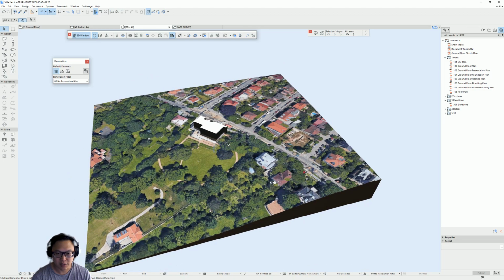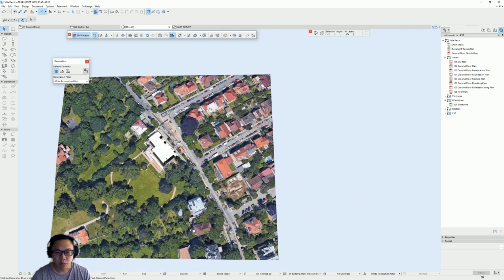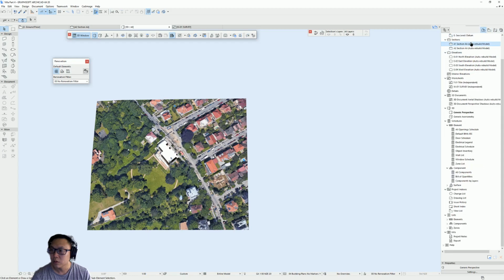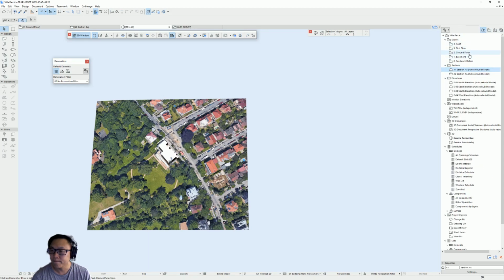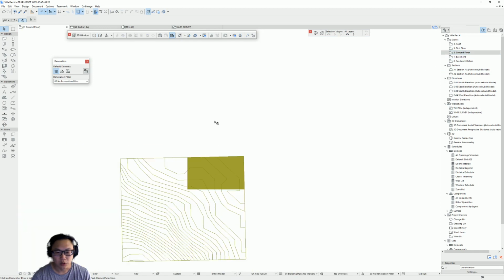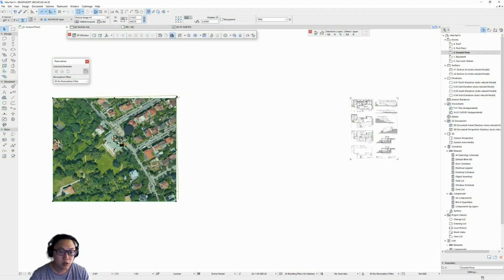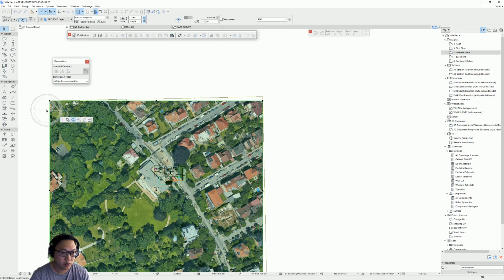It gives context, greeneries, and with that, let's say if we go back to the floor plan, ground floor, well, you can't really see it here, but what you could do is to bring the location image 3, drag it into Archicad, then just put that into the corner, stretch the image, and it needs to be rotated a little bit.